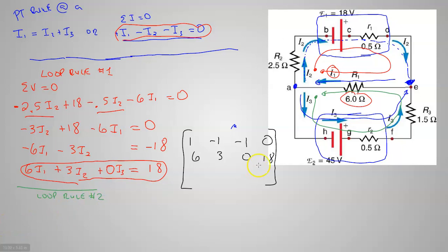Right there. All right, so let's see what happens. Starting at this point, there's no resistors, no batteries. Oh, here's a battery. Okay, that adds 45 volts. It's a battery, so that would be plus 45. Immediately after that, I cross a resistor. I have a drop, minus 0.5.